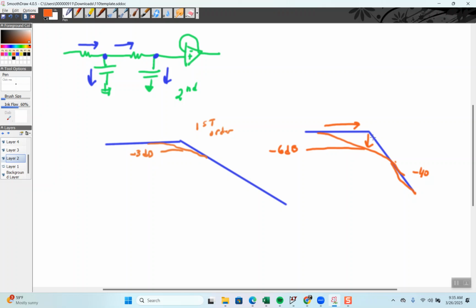But what's really happening is, I set the cutoff frequency, and the higher the order, actually it starts attenuating into the spot that I don't want. And that's because the best I can do, and that's really all that math, is critically damped. Right? Which means there are 2 repeated poles, minus 6 dB. And also I'm showing that if I choose certain ratios, I can easily design this.